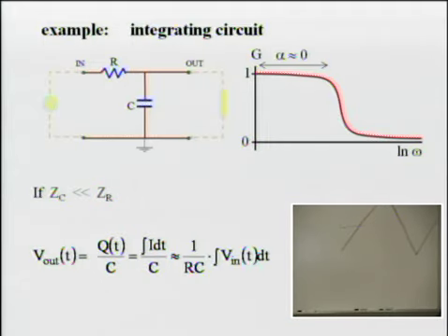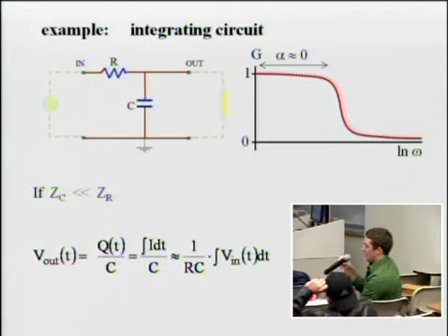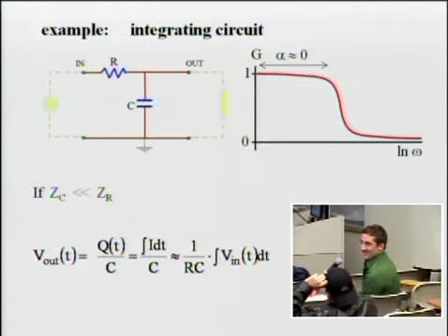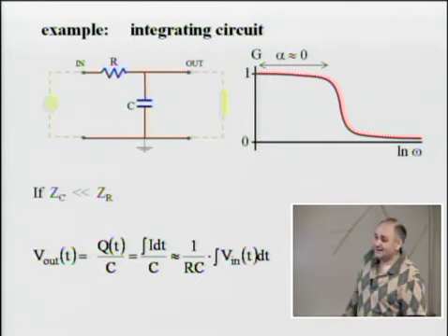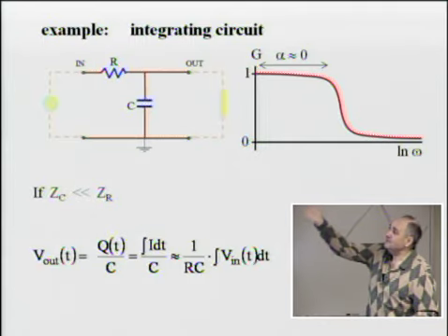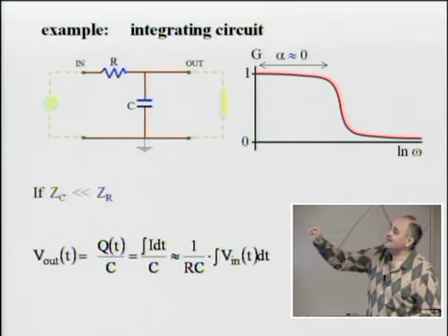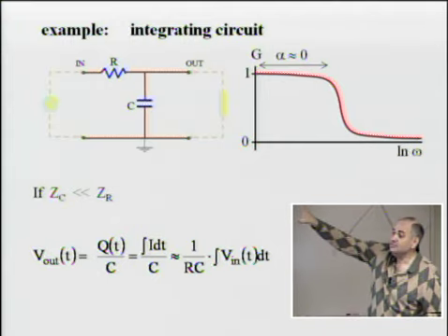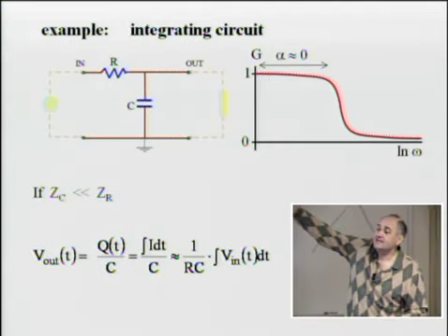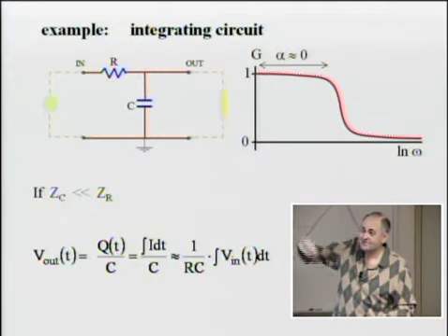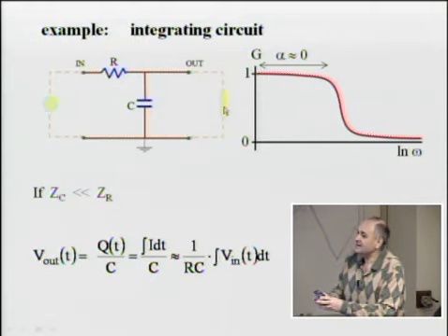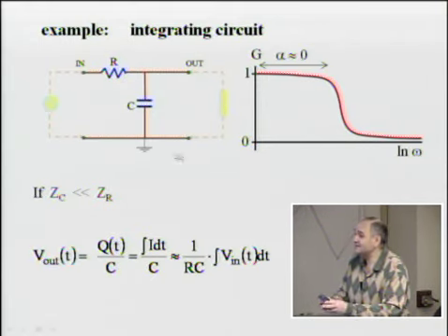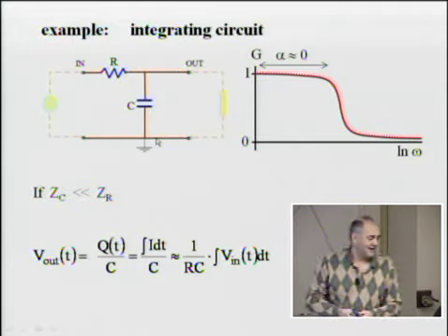My thinking is the capacitor never discharges then, it only charges. Very good. After some time the capacitor is only being charged, so the output potential goes up, up, up. It could kind of work if the load on the right-hand side, the yellow load at the amplifier input, has relatively low impedance, so that the capacitor has time to discharge. All right.